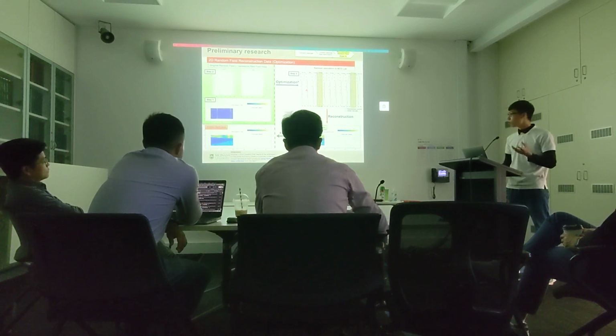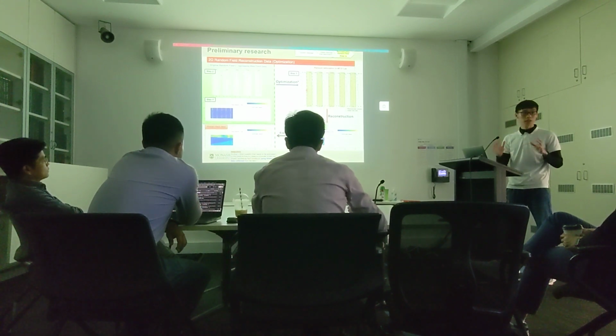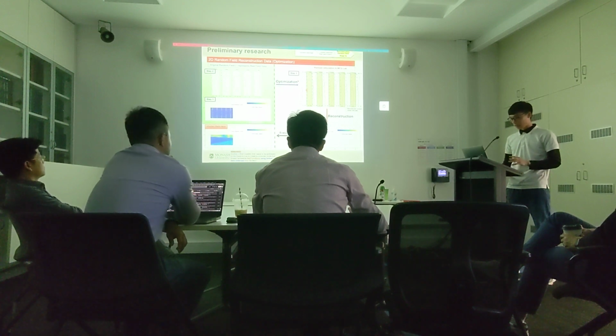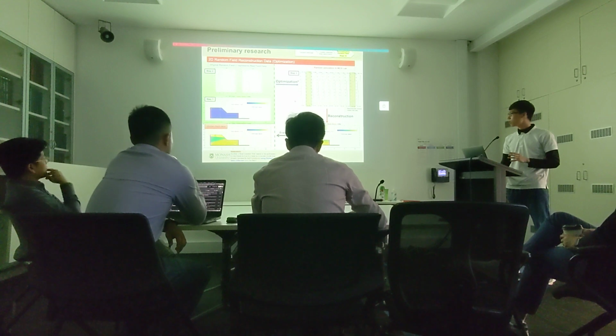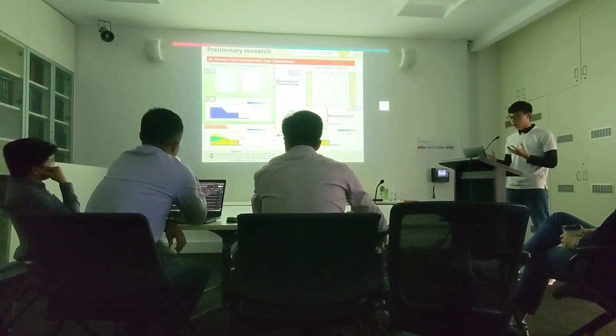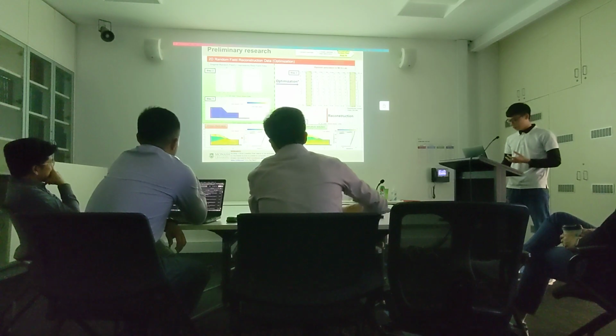And then 1 borehole, 2 boreholes, 4 boreholes, 5 boreholes. The more borehole information incorporated, the better the solution that we can have. And then we also incorporate in here the slope with 2 boreholes, we reconstruct here. We also set up some sensors basically to take these advantages for my next step. So I take the information to make the prediction better.